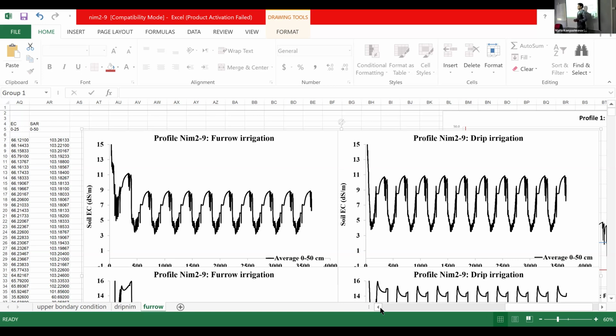So if we want to optimize the water management, we see how much water is needed for leaching, how much water is needed for irrigation. You have to evaluate this value. If the criteria are the EC and SAR, you have to evaluate those characteristics of the profile and say, okay, this amount would be the optimum, and you will deliver it to the farmer.